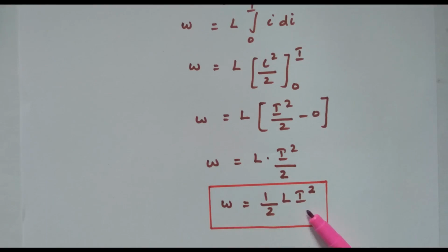So this represents the energy stored in the inductor, when the current is increasing gradually or decreasing gradually. In charging, the inductor is storing the energy, or discharging the energy, meaning the current increases or decreases gradually. In case of a capacitor, the work done is nothing but half C V square. In a capacitor, charging and discharging mean the voltage is increasing or decreasing gradually, right? So for the inductor, the energy stored W equals half L i square. Now we'll see the energy density of the inductor.